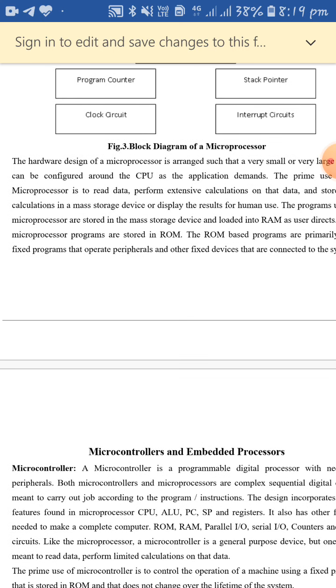Next, number of IO pins. How many IO pins are available, what are the multifunctions of each pin, and how many timers are there on chip. Next, the cost per unit, because this is also important. If you consider cost as a parameter, the final cost should not exceed the budget. Ease of upgrading is also important. Time to time you have to upgrade your systems whenever you want to add more parameters or applications to your systems.